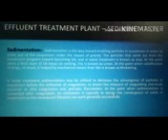In water treatment, sedimentation may be used to decrease the concentration of particles in suspension before the application of coagulation, to lessen the amount of coagulating chemicals required, or after coagulation and perhaps flocculation. When sedimentation is applied after coagulation, its purpose is typically to reduce the concentration of solids in suspension so that subsequent filtration can work most successfully.